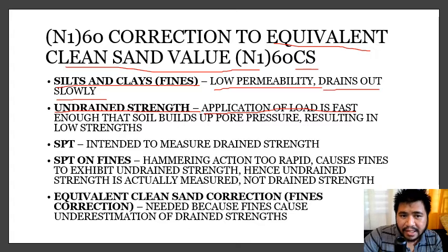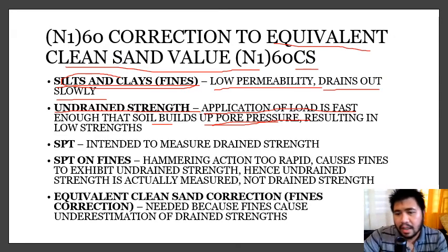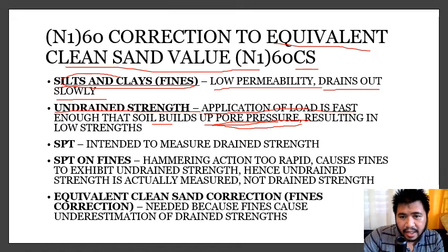And if your soils are actually fines, or silts and clays, there's a tendency for the soil to have pore pressure build up. And when you have a buildup of pore pressure, remember the effective stress equation: the more pore pressure you have, the lower the effective stress and the lower the shear strength.